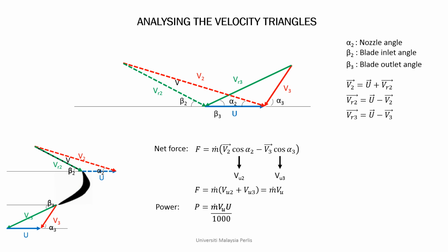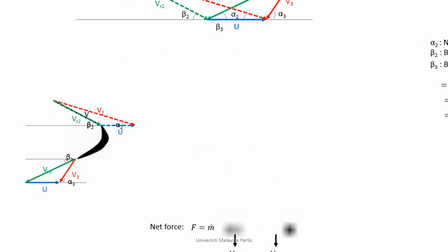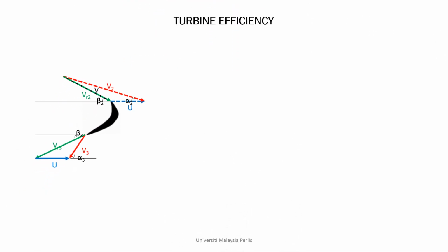Now we want to know what is the efficiency of this diagram, or the efficiency of the blade or the rotor. The blade is supplied with energy of half mv squared from the incoming steam flow. The blades are not able to convert all of the incoming energy because some of them will go with the output velocity.